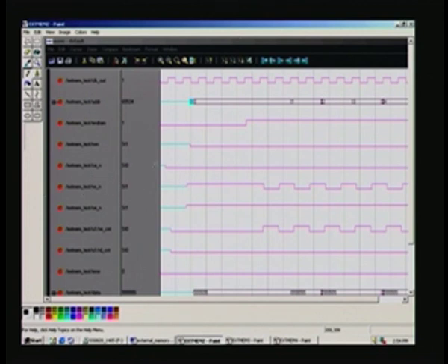So, for example, you need to select the chip, so we make the chip low, and the test bench we had made it here, and RW1 is in write mode, as we have seen it is low, and chip is enabled all through, and the write pulse is applied corresponding to the 0 address here. The write pulse is applied after the positive edge of the clock here, so that address is always applied at the positive edge, you can see here, and always at the positive edge address is changed, whereas the write pulse is applied only after the address stabilizes.